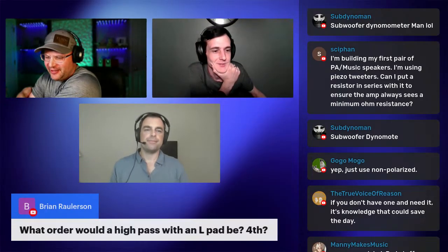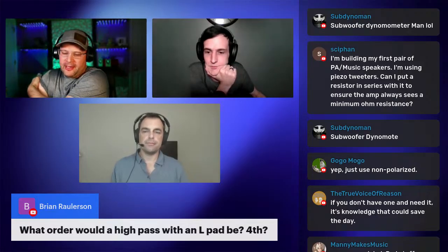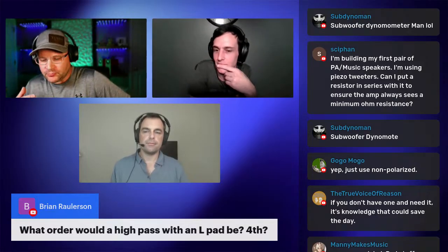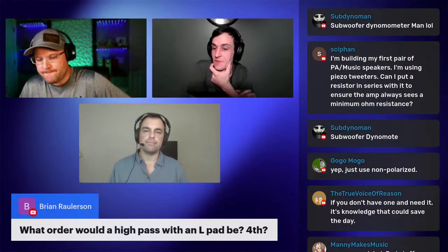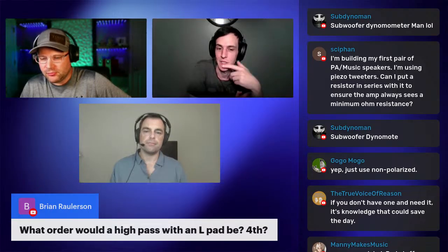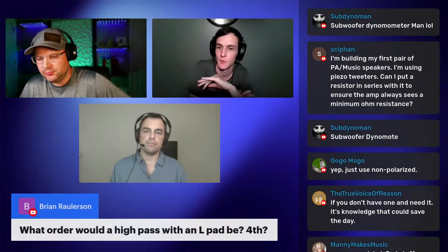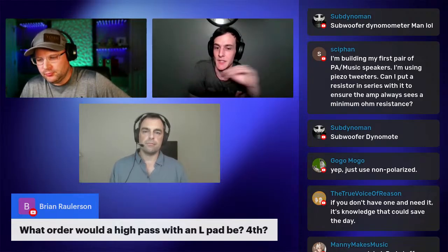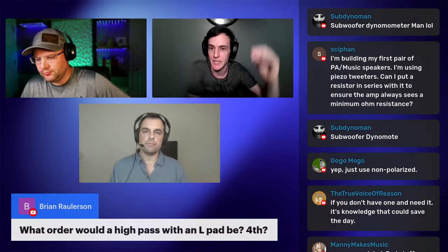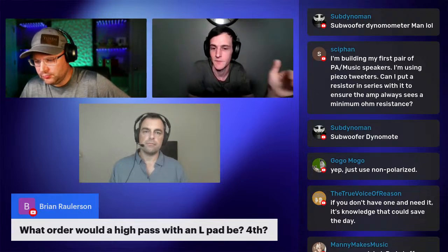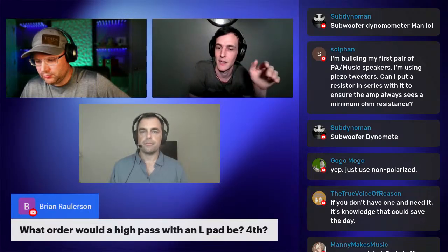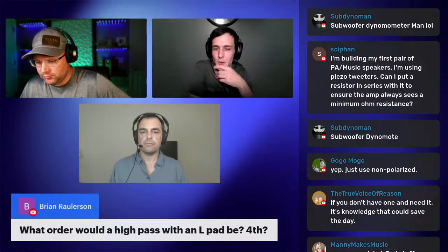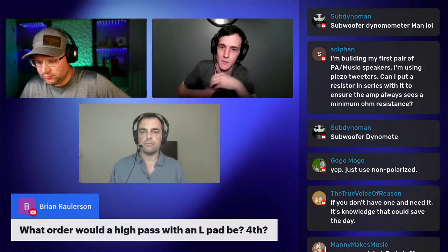All right, so here we go. This is a good question. This is by Brian Rollerson. He said, what order would a high pass with an L-pad be? If you're talking about a first order crossover with an L-pad in addition to it, it would still be a first order crossover. That's the electrical and acoustical roll-off, where a single resistor, or rather an L-pad, is going to attenuate the entire range, and it's not going to affect the acoustical roll-off per se. The series resistor can shape it in some ways, but it's not going to add to the order of the crossover.